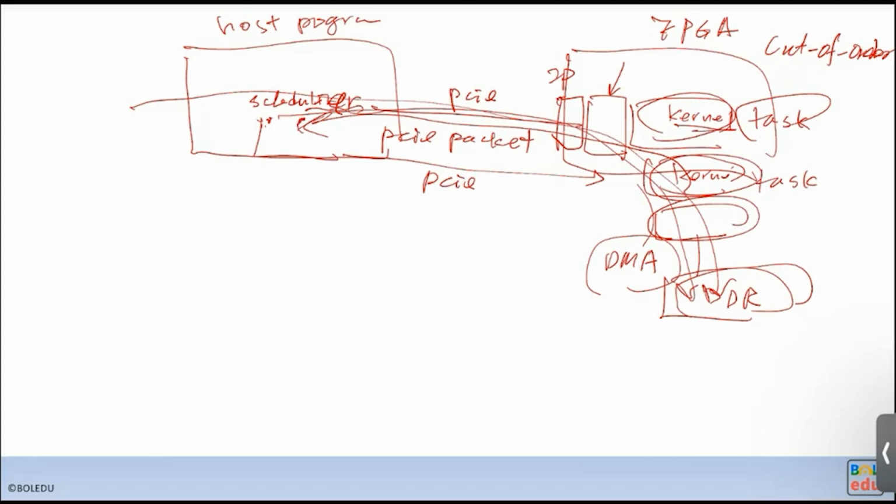So what's involved here is not just the hardware path. The hardware, of course, takes latency, especially PCIe. PCIe is a serial bus, so there will be serial to parallel to serial, all those transaction conversions. But what really is the overhead is the OS driver.